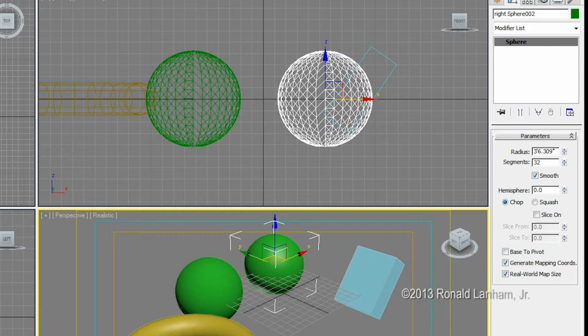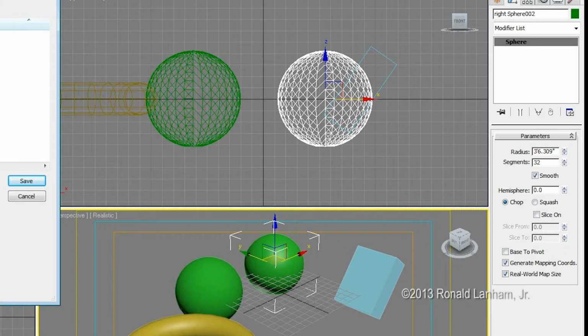You have the render output, which is where you actually set up the files that you want to output. In this case, let's say we want to create a PNG file. Let's go to desktop. We'll just call this test. Select our PNG image format. When we say save, it's going to bring up the configuration. You can have alpha channels, which we'll go over later. Again, you can have interlaced. I'm just going to keep the default settings and say OK. Now when I render the image, it will save this test PNG.